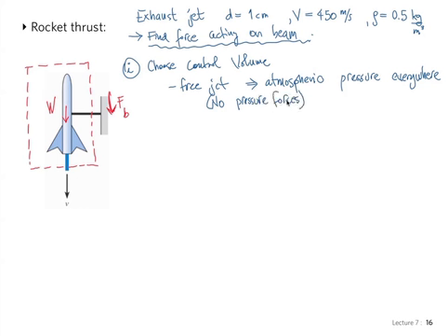And the other one was shear stresses, but we don't have any shear stresses either because this is not moving, there's not rubbing against anything, there's no friction against anything. The jet is free, it's just coming out of our control volume with no friction. So that's all we have. Okay, we chose the control volume and drew our forces. We're ready with that.